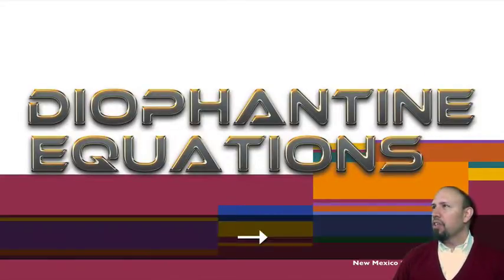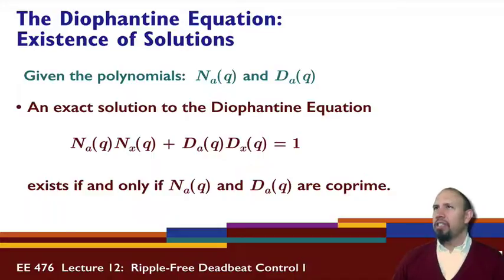Diophantine equations. So what's the deal with Diophantine equations? Here we're going to assume that we have the polynomials NA and DA. Remember, we have two different Diophantine equations we're working with, each with a numerator term and a denominator that are known polynomials. We want to find an exact solution to the Diophantine equation. So NA and DA appear in here. We're going to have an NX and a DX. Those are the solution polynomials, such that all of this is equal to 1.